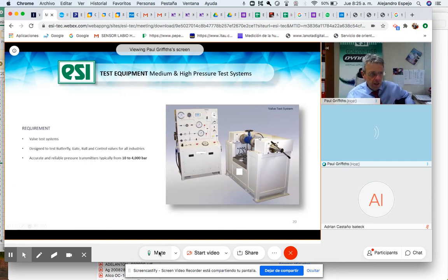So quite often in tests like this, you'll have perhaps a sharp rise in pressure, or alternatively, a sudden drop in pressure. If you were doing hose testing and the hose bursts, you get a very quick drop in pressure, and sudden increases and decreases can damage pressure sensors. And because of the robust structure and the titanium, it's very difficult to damage an ESI sensor this way.